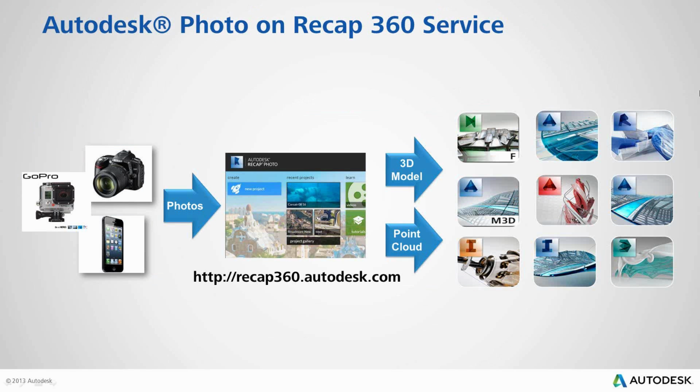So the ReCap 360 Photo service, how does it work? Again, you start by taking photos from any type of camera. We also support the GoPro Hero 3 Plus Black Edition, the one that has the 12 megapixel sensor. Please do not use any other one. When you use a GoPro, please also use it in time-lapse mode with still images, not with the video. Otherwise, it works very well. The advantage of the GoPro is that it has a fisheye lens, something like 127 degrees, so you can really capture a lot of information in each of the photos. So overlapping is made much easier.